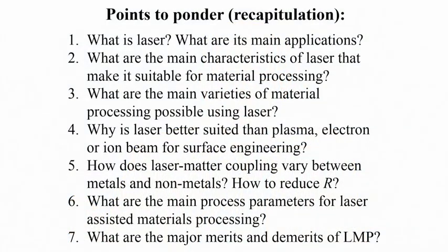There are two main variables we are talking about. One is the interaction time, the other one is power density, and by varying these two parameters we actually can cover a very wide range of materials processing. We always consider laser to be a better suited agency for material processing, particularly surface engineering, than plasma, electron and ion beam because of the exponential nature of decay profile of the incident energy.